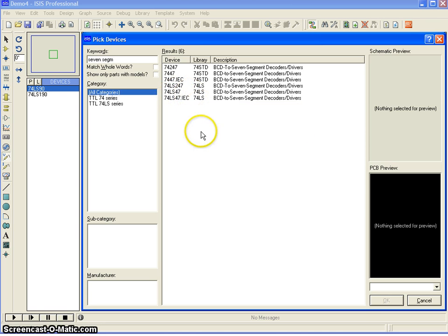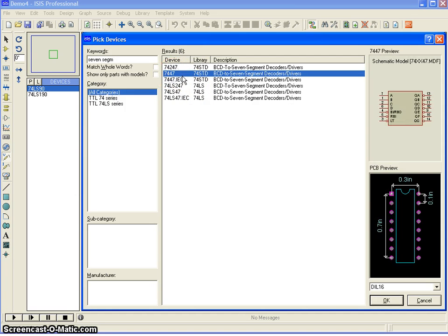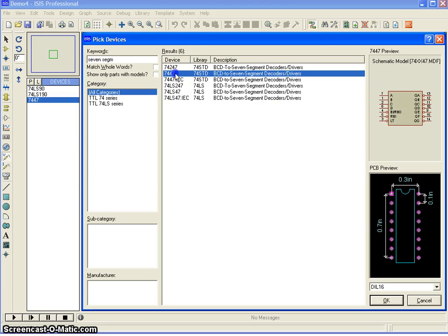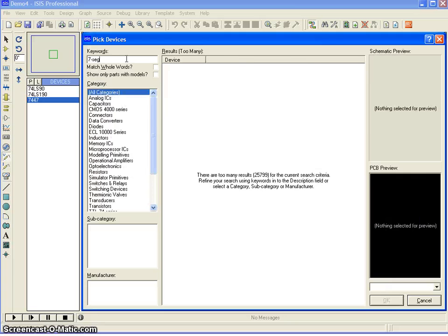Yeah, we should actually have the driver in real time, whereas in a simulation environment you can even connect the output of the counter directly to the 7-segment display, whereas in real time we need to have a display driver. This is called a display driver. Okay, we should have a display driver and 7-segment.